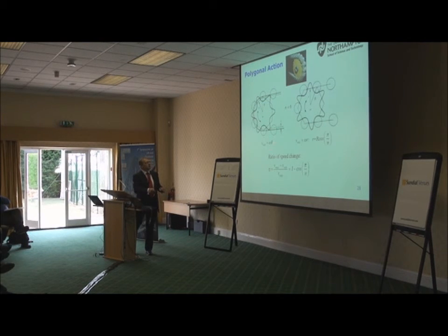When you multiply this by the larger radius, we get the maximum value of velocity. On the other hand, when the chain moves a bit further, the velocity is expressed through the same frequency, but the smaller radius. And so we have different velocities which fluctuate.